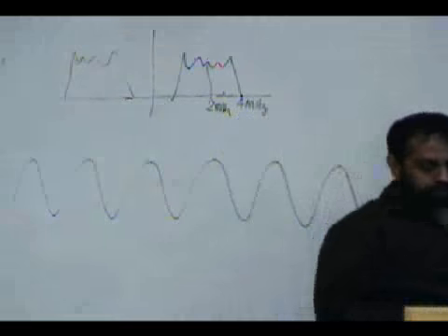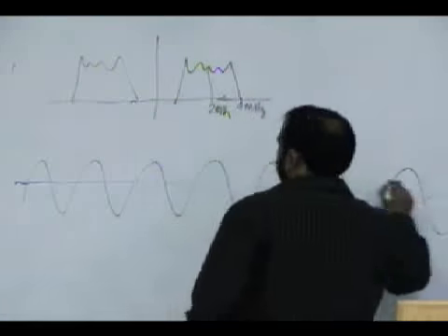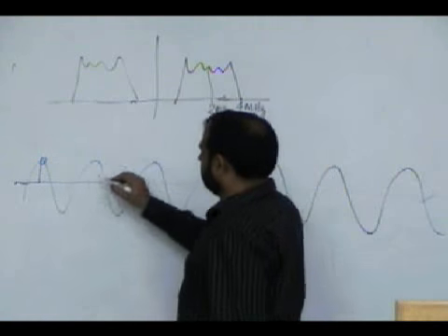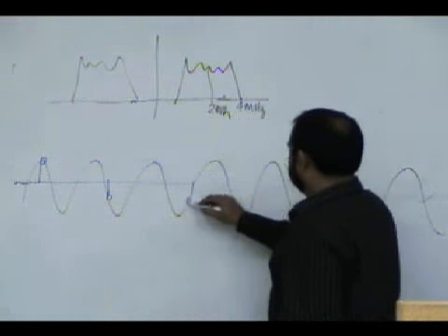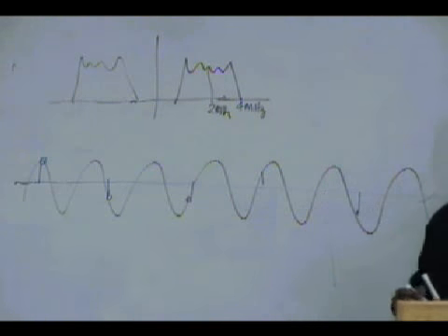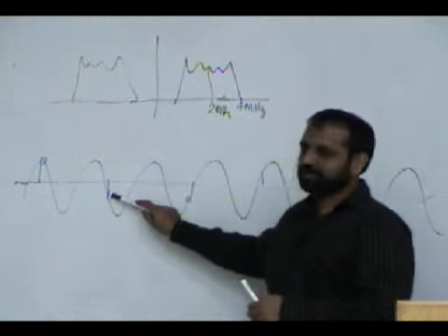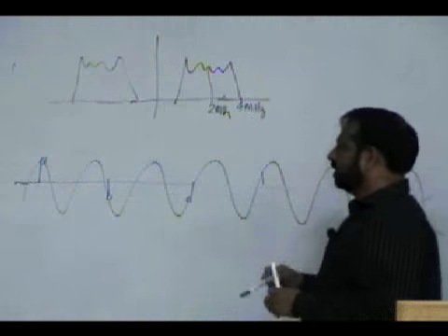So I have an A to D converter which samples and tries its best, goes here. This is the best it can do. Okay? So no 2 samples in a cycle. It takes a sample here, then comes back here, comes back here, comes back here.